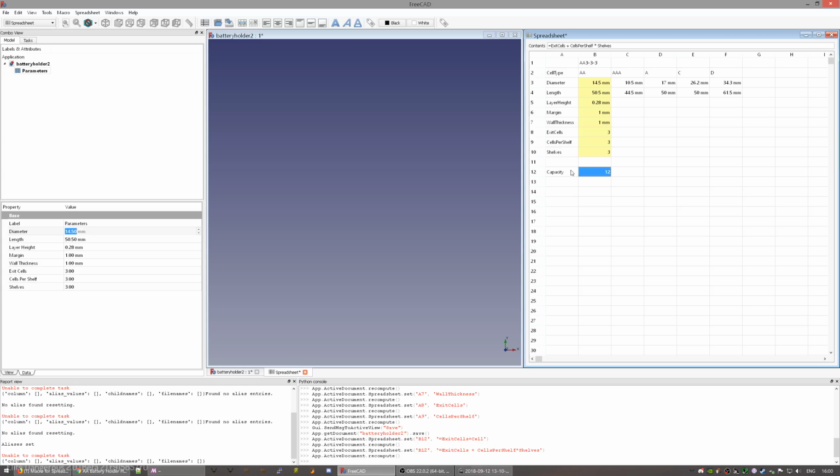But that's for later. We can place some parameters here that are just informational, but one of the weaknesses of FreeCAD is that when connecting data fields like these, a spreadsheet is regarded as a single unit, so any update to the spreadsheet will cause anything that depends on that spreadsheet to update, and vice versa.